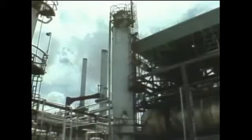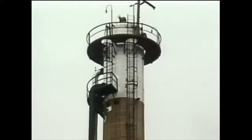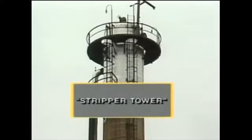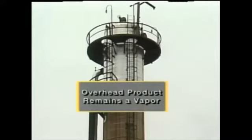For some product specifications, it's necessary to separate light components to control the product's initial boiling point. To meet these specifications, some processes use distillation towers called stabilizers. Another type of tower is called a stripper tower, because it strips lighter components out of the products. However, unlike most other distillation systems, a typical stripper tower system does not condense the overhead product into a liquid. Instead, the overhead product remains as a vapor and is sent for further processing.